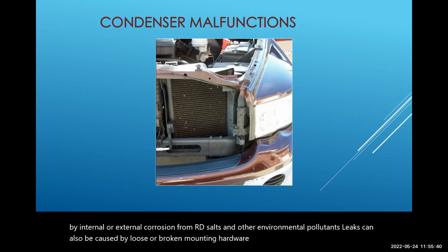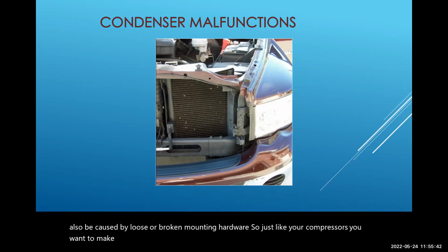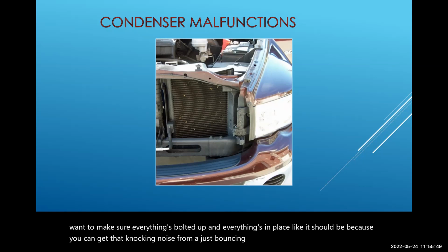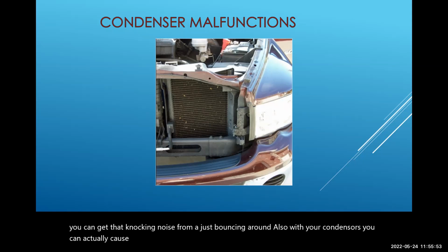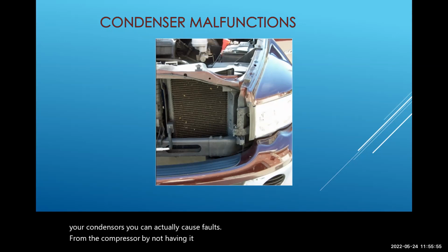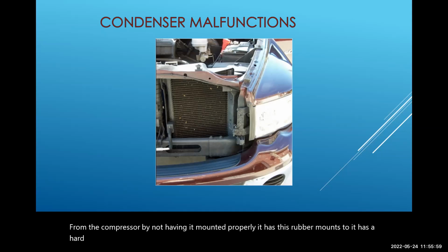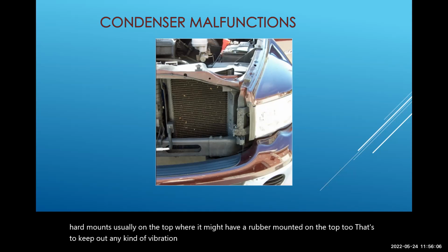So just like your compressors, you want to make sure everything's bolted up and in place like it should be, because you can get that knocking noise from it just bouncing around. Also, with your condensers, you can cause faults by not having it mounted properly. It has rubber mounts, and usually hard mounts on the top, or it might have a rubber mount on the top too. That's to keep out any vibration that might damage it.